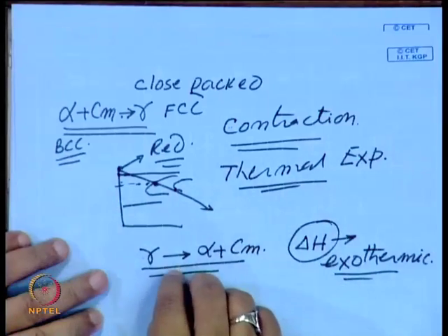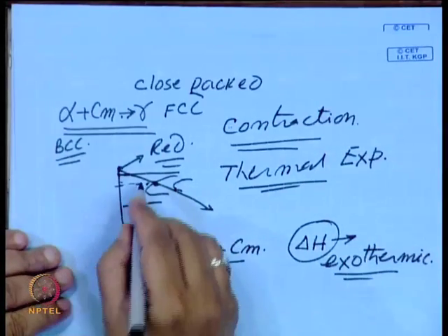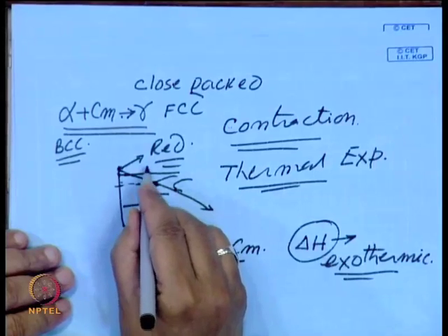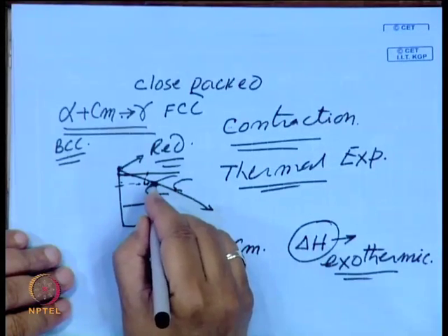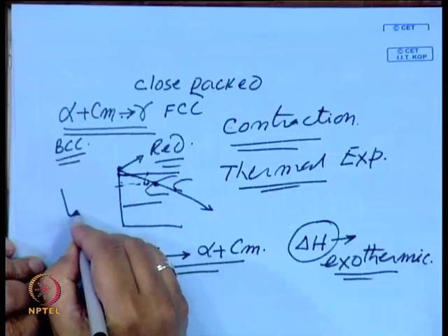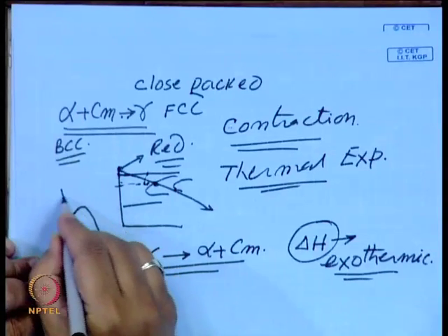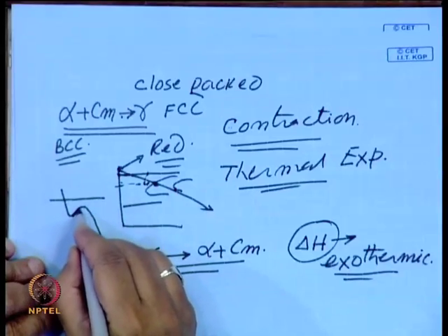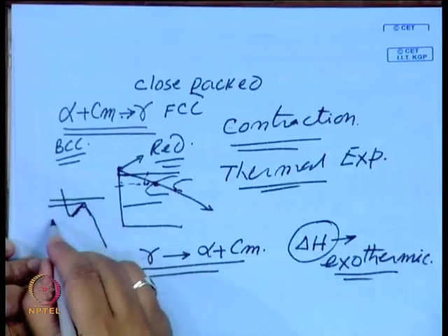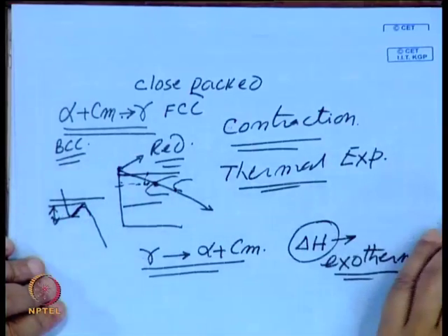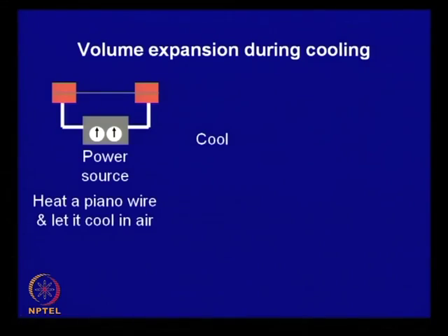Therefore, it gets heated up again, and you may question whether it will exceed the earlier temperature; that does not happen. But when the temperature is going down, suddenly it gets heated up and then cools again. Your eutectoid temperature is possibly here, and this rise is large enough to make it red again, and that is what you will see.